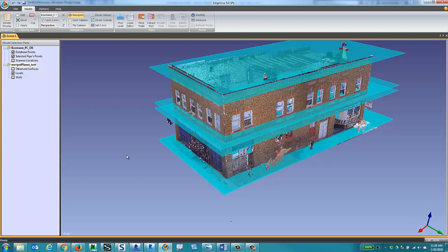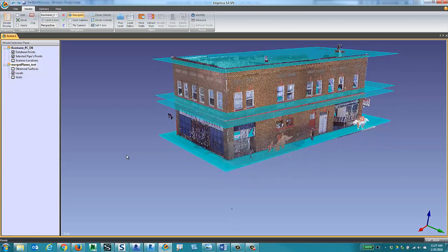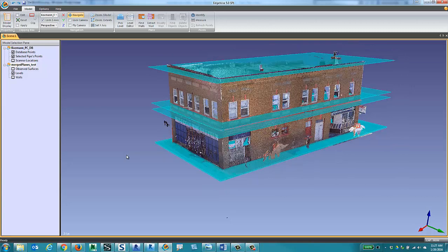So it's not the best way to do it. The best way is to have that data captured in the field, and sometimes you have to place artificial targets for this, right? Some people will place a flat surface, bent metal, anything outside, so they can extract a surface off of it and don't have to rely on picking points. That works pretty well. Once you've done that, the whole thing kind of looks like this.